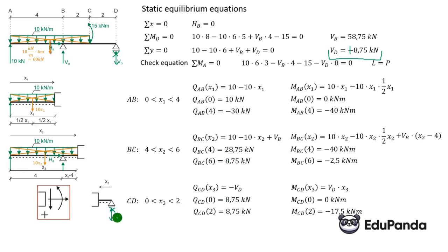Well, so we would write this equation again. The force is directed downwards, so the shear forces downwards are positive forces. So I would have plus VD here. And I look, the reaction value VD is 8.75, okay, I write 8.75, no problem. Next, regarding VD against this pull moment, as if this cut, it rotates clockwise, so it's negative.